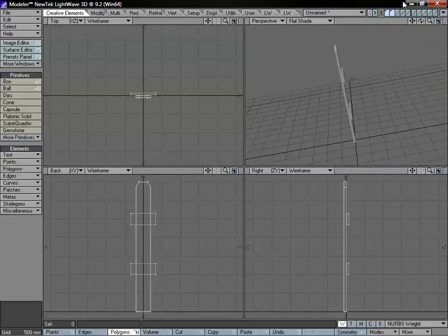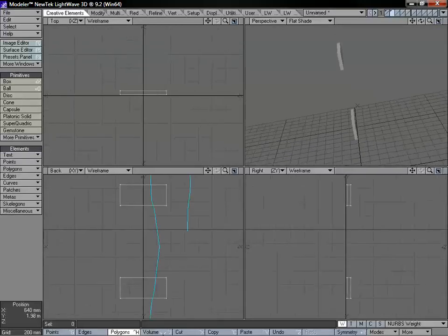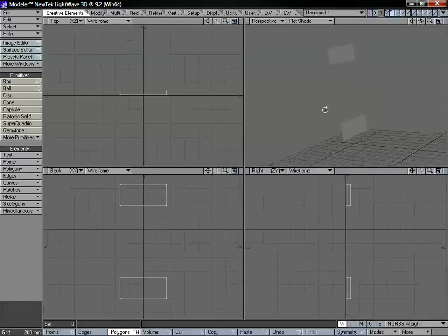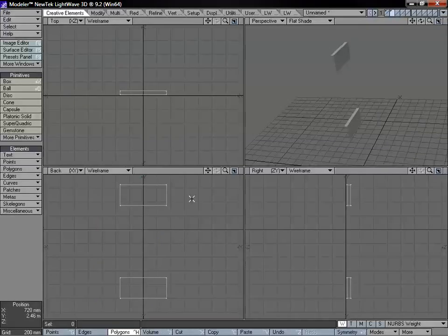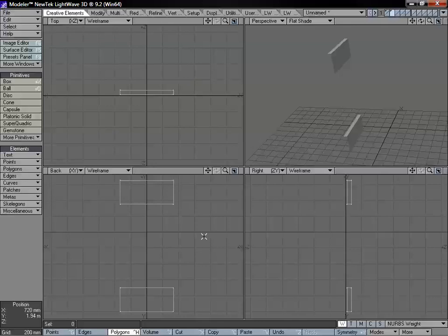And that looks pretty good. All I really want to do now is just add that bit of bevel. So I'm going to delete our side polygons because we don't need them. Because all of our fence sections are going to be connected at these points right here, as if they were mirroring each other, kind of like how the vector clone works. So we don't really need those polygons in the scene.